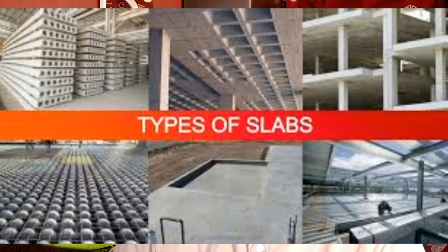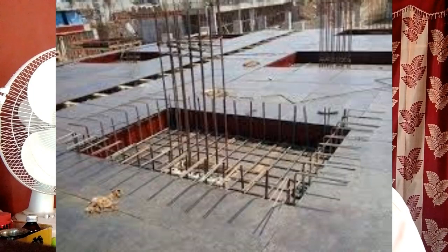Next point is, how thick is a normal house slab? A slab foundation is made of concrete that is typically 4 to 6 inches thick in the center. The concrete slab is often placed on a layer of sand for drainage or to act as a cushion. Houses built on a slab lack crawl spaces and there is no space under the floor.